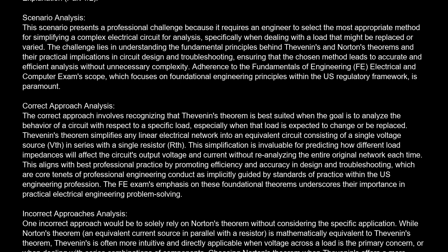Incorrect approaches analysis. One incorrect approach would be to solely rely on Norton's theorem without considering the specific application. While Norton's theorem, an equivalent current source in parallel with a resistor, is mathematically equivalent to Thevenin's theorem, Thevenin's is often more intuitive and directly applicable when voltage across a load is the primary concern, or when dealing with series combinations of components. Choosing Norton's theorem when Thevenin's offers a more direct and conceptually simpler path to understanding load behavior could be considered inefficient, though not necessarily a regulatory failure in itself.